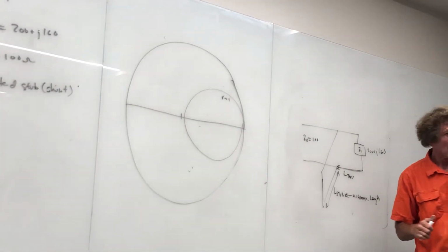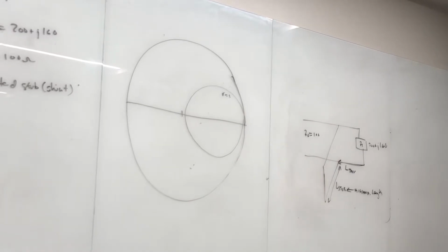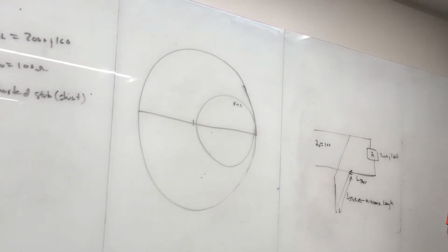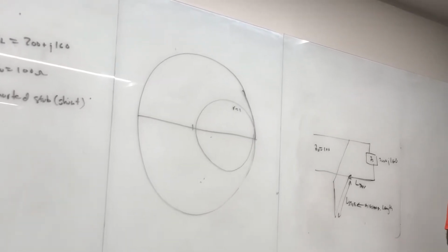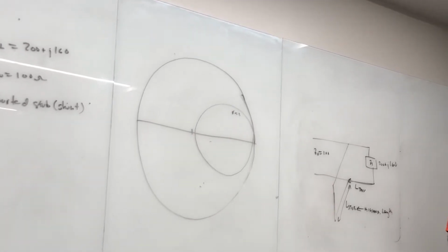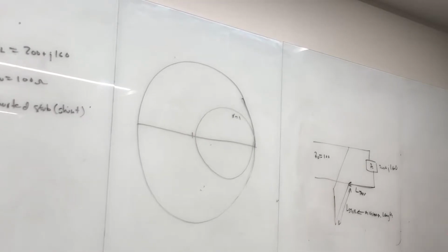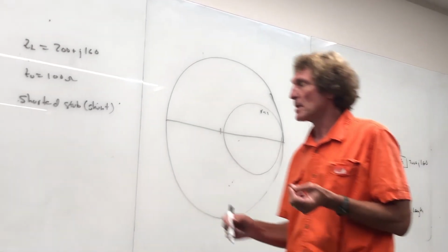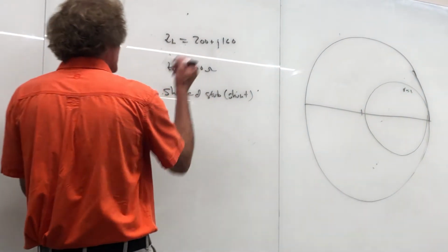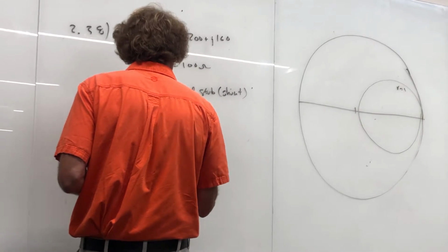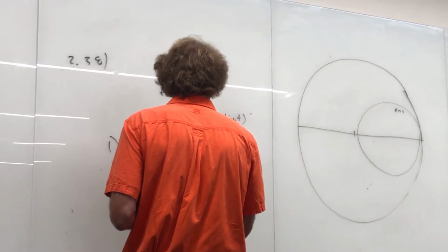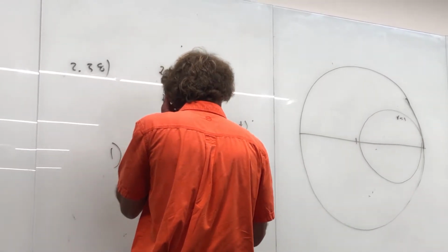That's his goal. All right, when you do a Smith chart problem, this is in shunt, so we're going to be working in the Y domain, the admittance domain, not the impedance domain. You agree, class? Remember, if we add admittances, they're like resistors in series, or they're impedances in series, correct? Y'all remember this? So let's start this problem out. First thing we do is find small zL, and that takes big ZL divided by Z naught, the characteristic impedance. In that case, it's what? 2 plus j1.6. Do you all agree with me there?